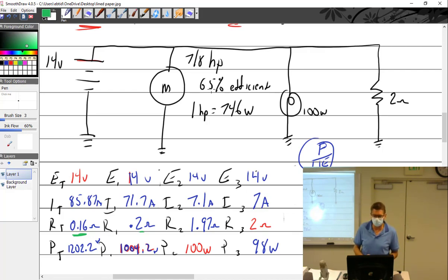You would put it all together, and then together with this load analysis, based upon the rest of the aircraft, you would submit this to the FAA. Back in the day, they used to do this thing called field approval. I remember days where I had an airplane, a low-wing airplane, with Form 337s, major alteration repairs, taped to the wing all the way from the root to the wingtip, with stuff that this aircraft had done to it that was just not approved, crazy stuff.